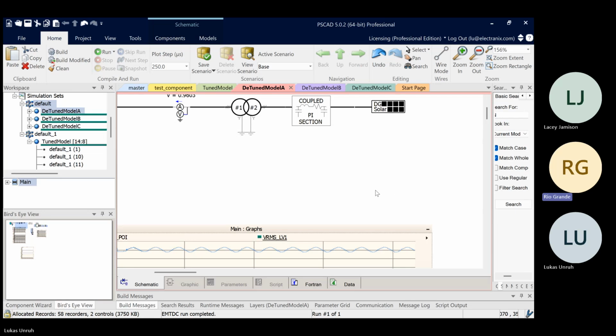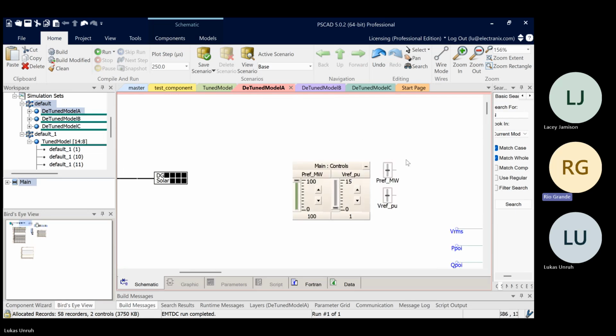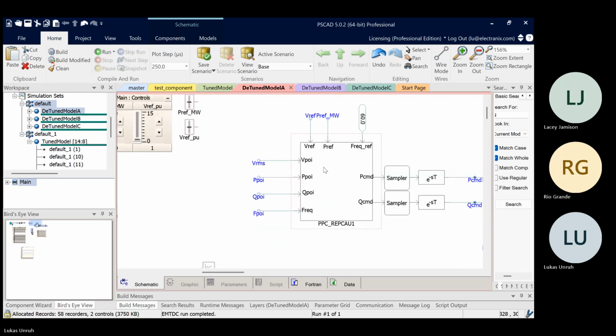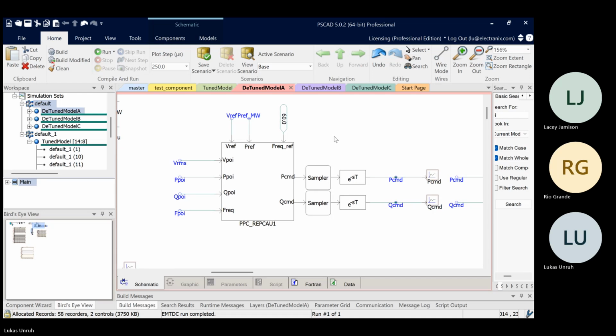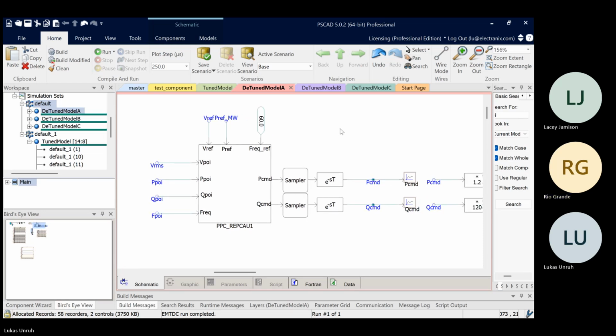So for this one, we could fix this in a number of different ways. One would be just to detune the voltage control loop, just turn down the gains, and that would make this go away. So just slugging the voltage control loop is going to help a lot here. The downside, of course, is that you might now have slow voltage control. Maybe it's too slow.